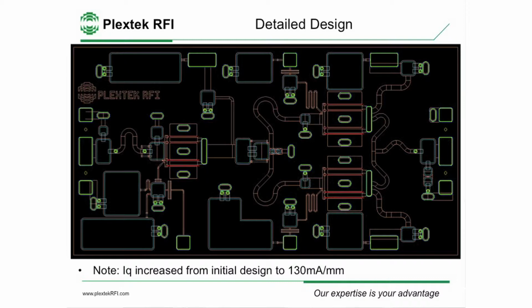What we tend to do, this is for the lower frequency decoupling, and what we have is a resistor to a capacitor. The whole aim of this is just to kill that gain at lower frequencies.